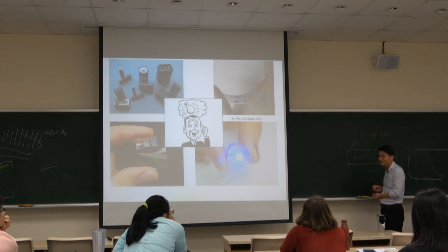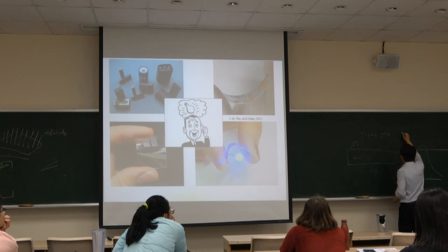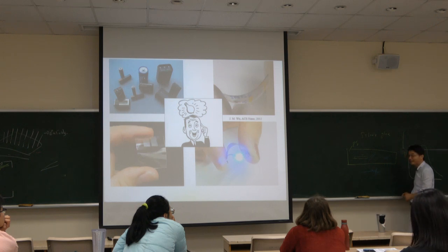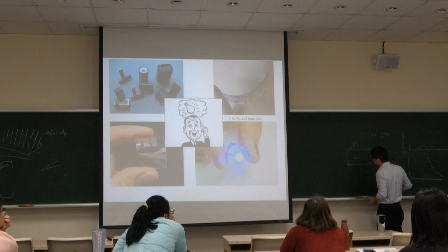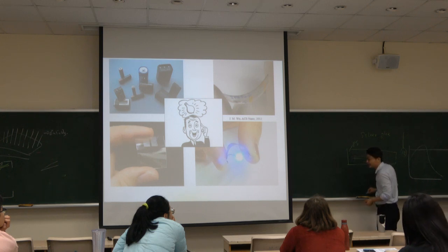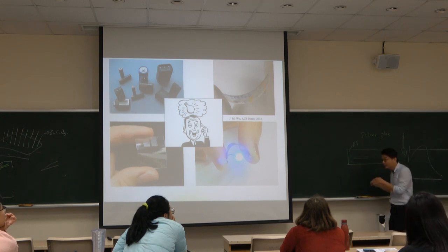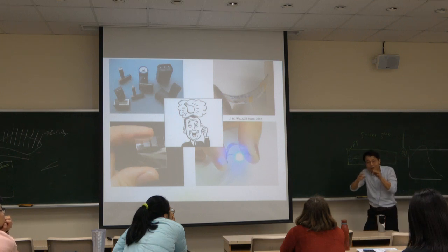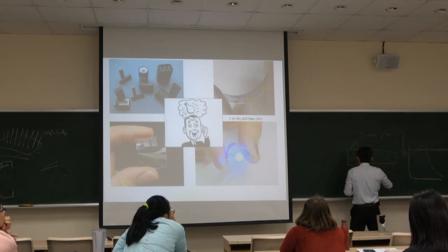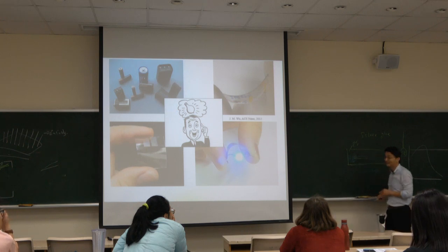This is the solution, okay? So you can pick up a drop of silver glue, and under the microscope, transfer the silver glue to drop onto the substrate here. This silver glue will diffuse progressively because it is a solution with high viscosity, so it will diffuse to touch this nanowire.